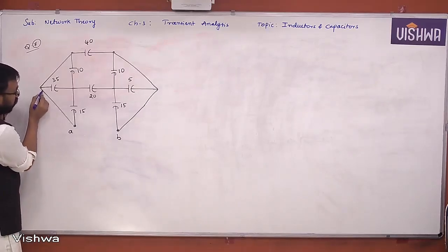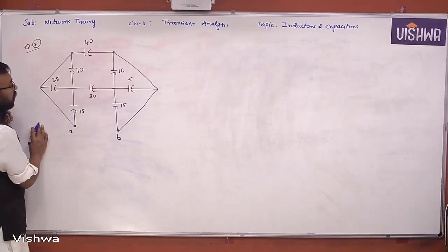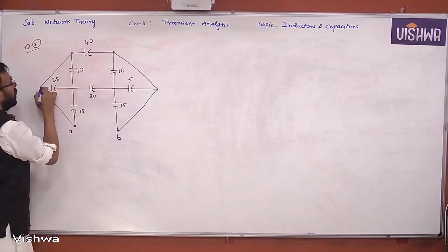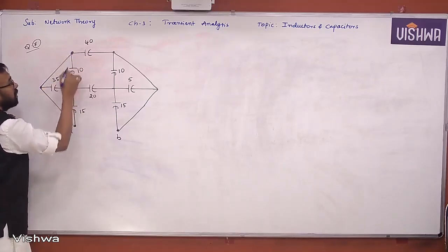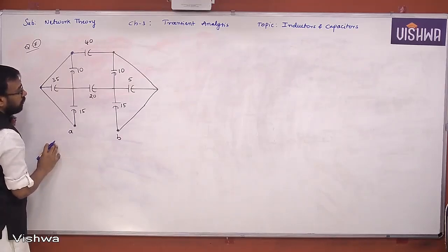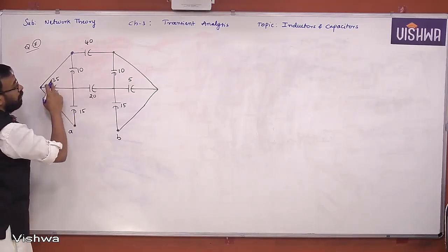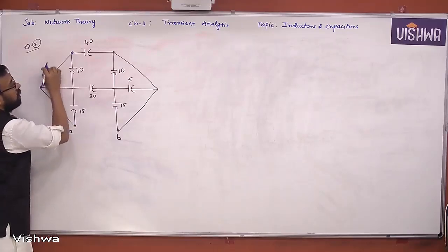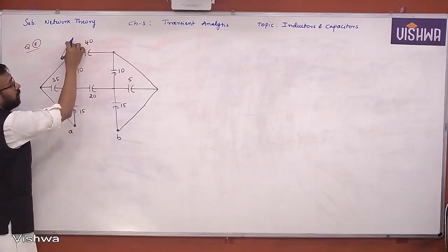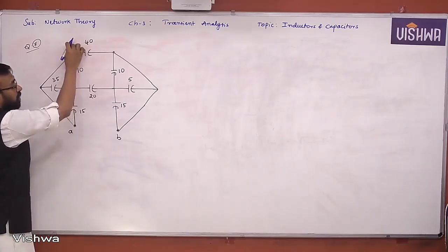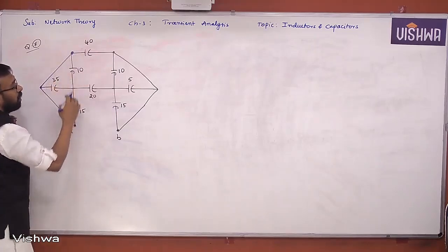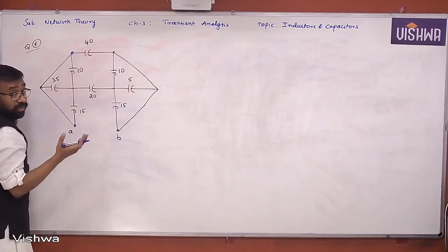Since this is a zero resistance wire connecting between these 2 points, and this element is also a zero resistance wire, probably this point and this point both are operating at same potentials. Yes or no? Even this point also. Now, can I say these 3 are connected in parallel? If I take this one here, and this one here, and finally this A is coming to this particular point. Yes or no, all of you? Or else you can bring this element to this element, all these 3 can be connected here. Anything is okay for us, not a problem.